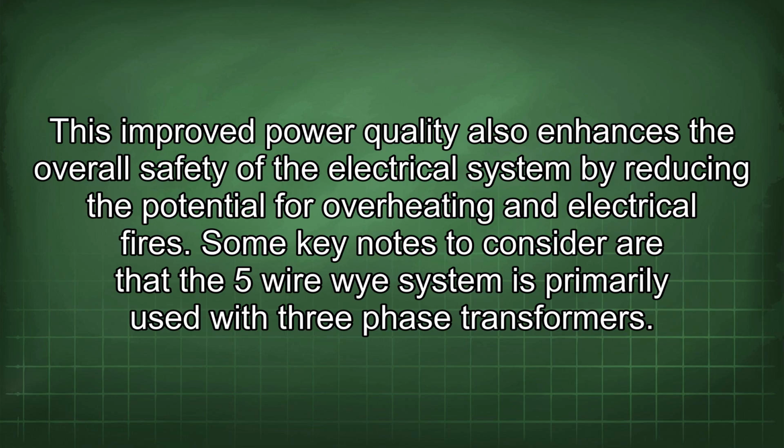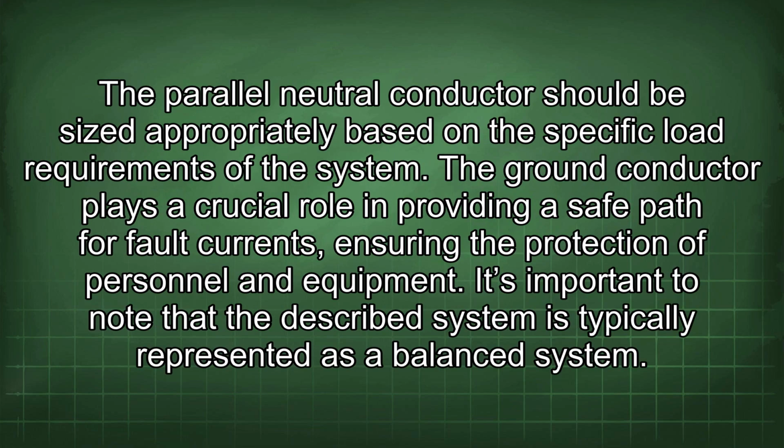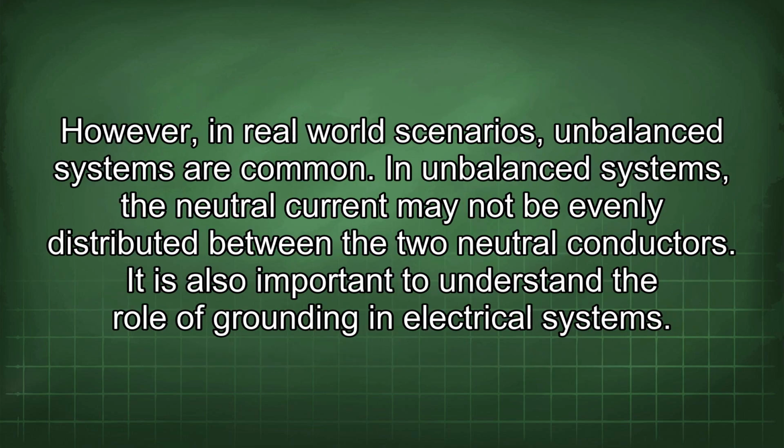and electrical fires. Some key notes to consider are that the 5-wire Y system is primarily used with three-phase transformers. The parallel neutral conductor should be sized appropriately based on the specific load requirements of the system. A ground conductor plays a crucial role in providing a safe path for fault currents, ensuring the protection of personnel and equipment. It's important to note that the described system is typically represented as a balanced system. However, in real-world scenarios, unbalanced systems are common. In unbalanced systems, the neutral current may not be evenly distributed between the two neutral conductors.